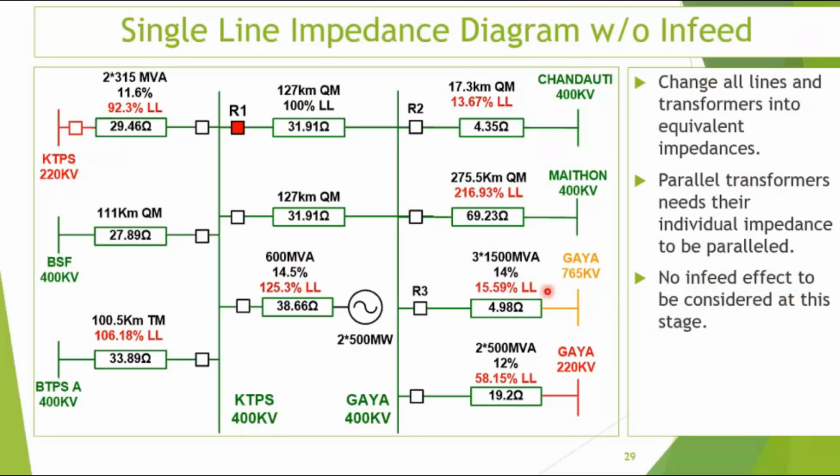They are not like the other utilities probably, including mine, where a lot of maloperations take place. I'm not blaming anybody. I'm not putting down anybody. But since that is a power grid substation, we are taking the risk that okay, let my zone 2 encroach. I don't have any problems. This substation has been commissioned for, let's say, 10 years.